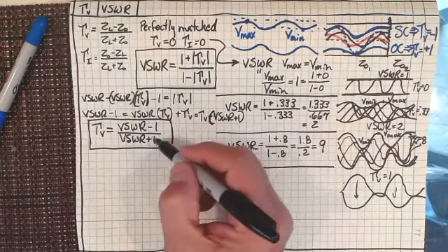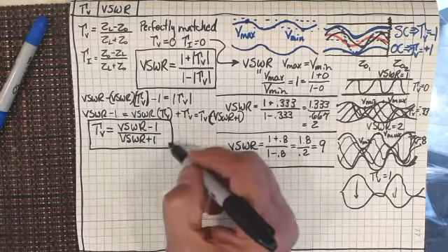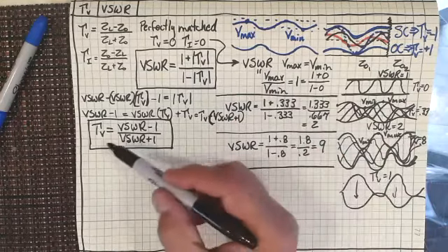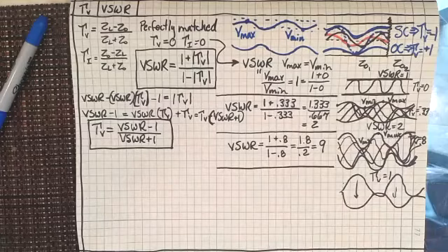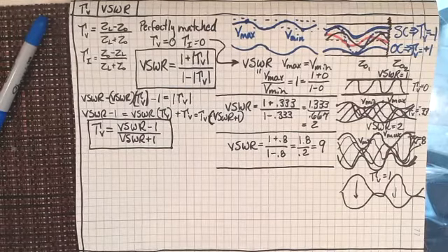So if I have a VSWR meter, I can figure out what my reflection coefficient is, and I can then work to solve that. And that would also tell me what the impedance mismatch really is too, isn't it? And if I know what the characteristic impedance of the line is, it indirectly tells me what the impedance of the antenna is too, doesn't it? So I think everybody can see that.